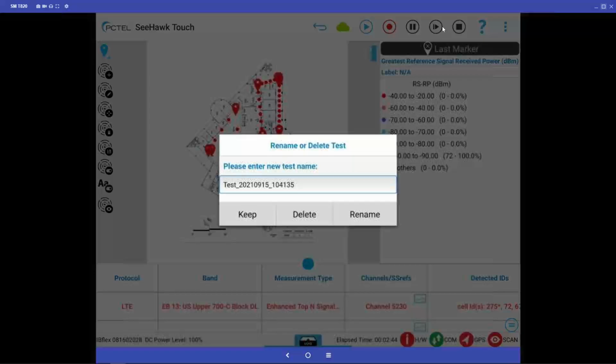The number of channels you select is going to be directly proportional to how fast you need to walk. And what I mean by that, if a nice comfortable pace is about a measurement per second, and that's in that 12 to 15 channel range. Once you get above 15 channels that you're doing a decode on, you're going to have to walk a little bit slower. And like I said, I think the maximum for commercial wireless is like 24 channels. If I'm doing 24 channels, I'm going to mosey around the building. I'm not going to be in any hurry to go anywhere, just to make sure I get enough data density between that.